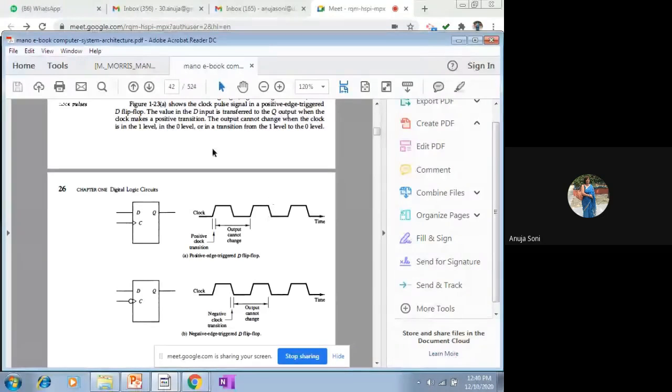So the flip flop, which has generated some value at the tth timing signal, that may be reused as the input value in order to generate the subsequent output value at the t plus 1th timing signal. So here we are going to observe the behavior of the next output variable in the next timing signal with respect to the previous output variable.